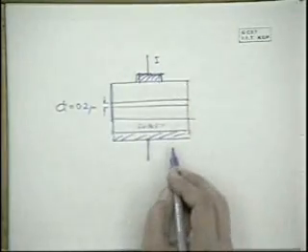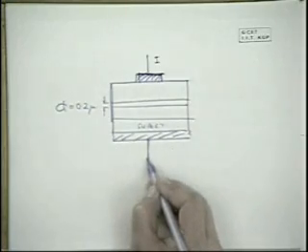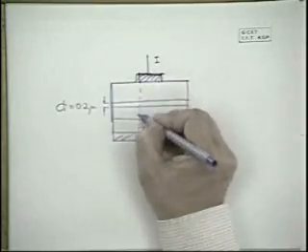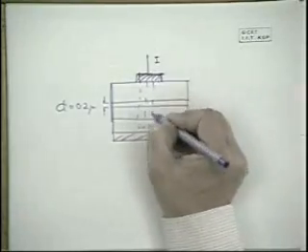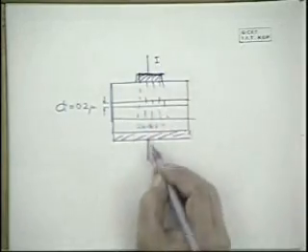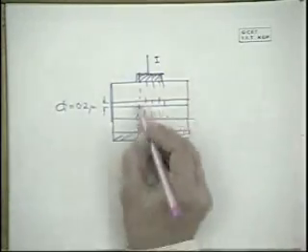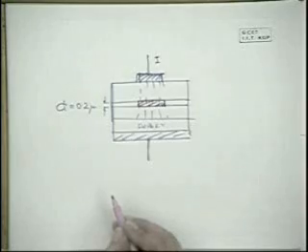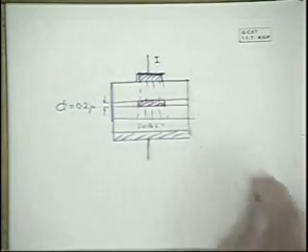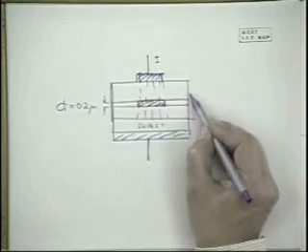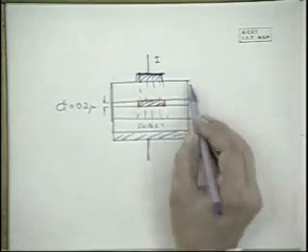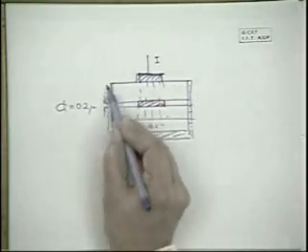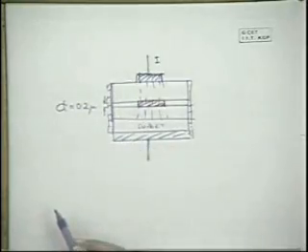This is important when we do calculations later on about the threshold current density. The current actually flows: if this is 100 microns, this is only 10 microns, so the current lines flow like that. The actual region which is emitting is only a rectangular aperture like that. The advantage is that you're not having current at the surface. You can coat the surface and make it passive, but the current does not flow, so surface recombination does not play a role.